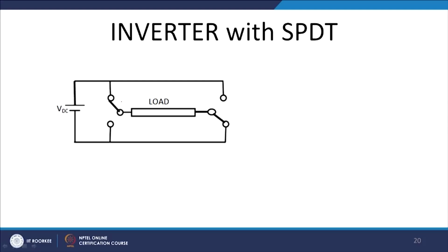So, this is the pole of the inverter and these are the two terminals 1 and 2, and these terminal points are A and B. So, the voltage AB will be connected to the positive DC bus voltage if point A is connected to point 1 and similarly point B is connected to point 2. So, we can change these points, thus we can change the voltage across it.